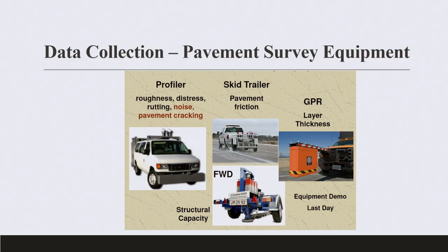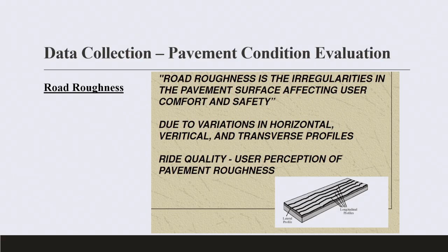So these are some of what we have, again, like measuring the skid resistance, ground penetrating radar for what's below, like layer thickness, like voids, and the profilers, and this is more or less like the ARANs, which depend on LiDAR. So LiDAR is for surface conditions, GPR for below conditions. We had that yesterday in all of our preservation.